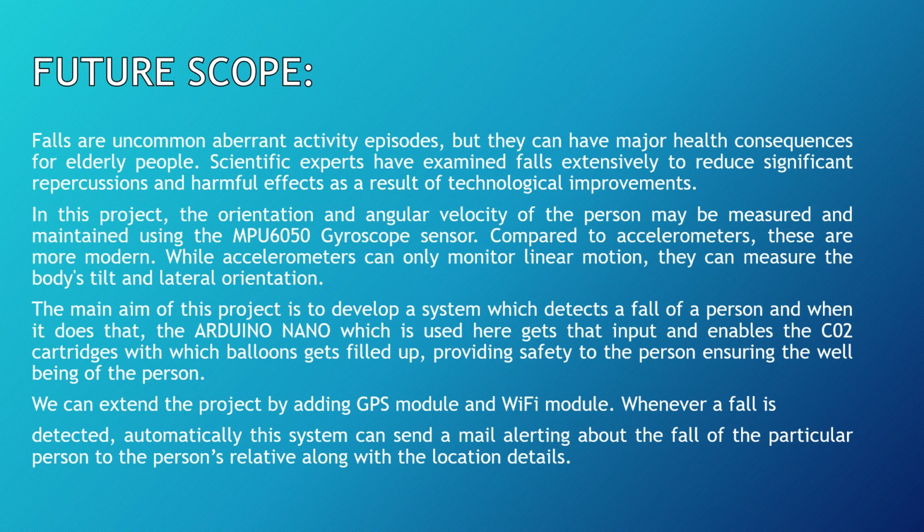The main aim of this project is to develop a system which detects a fall of a person. When it does that, the Arduino Nano which is used here gets the input and enables the CO2 cartridges with which the airbag gets inflated, providing safety to the person, ensuring the well-being of the person.